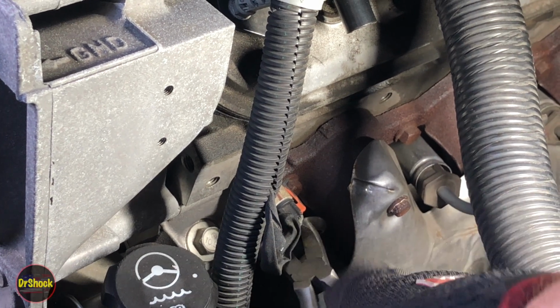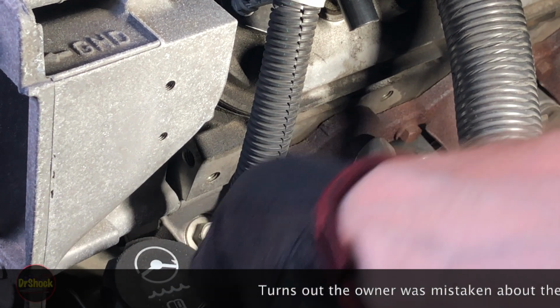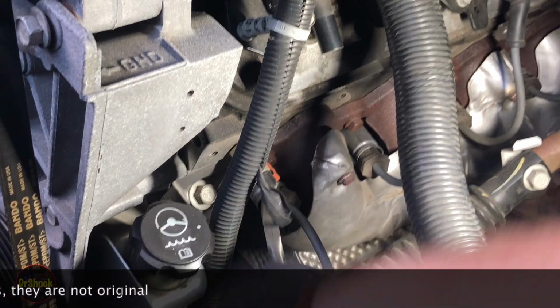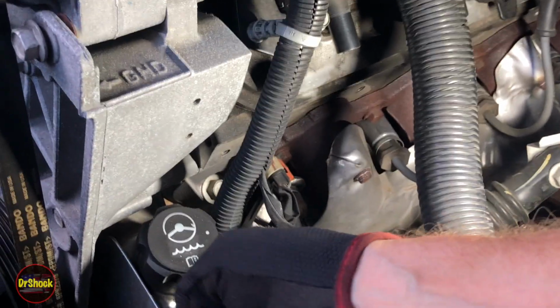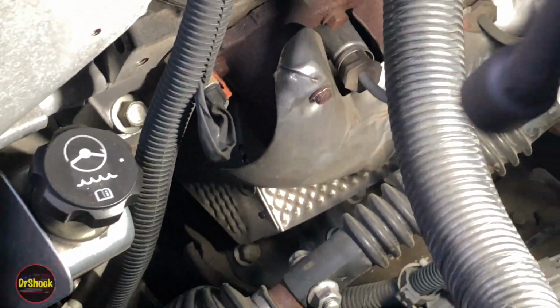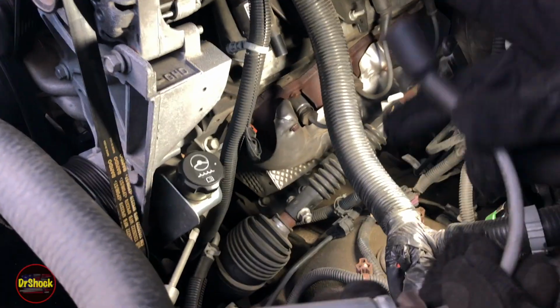This is also still running on the original coils and the original ignition plug wires, so there could also be something going on there, but less likely. When you grab these things, just grab them by the metal shield, never by the rubber. And when you pull something like this, make sure you don't have the tool wrapped around the wiring harness for the sensor. So the first thing we're going to do is we're just going to inspect the wiring.